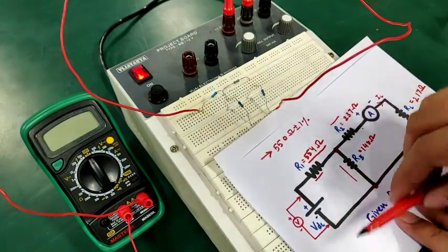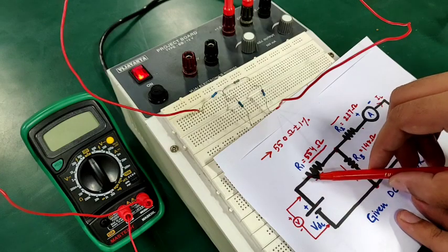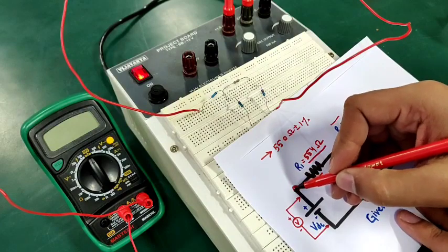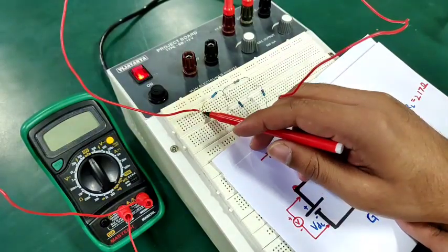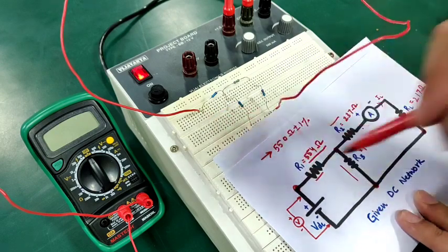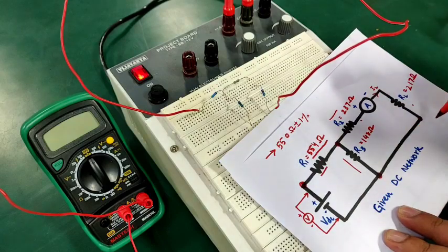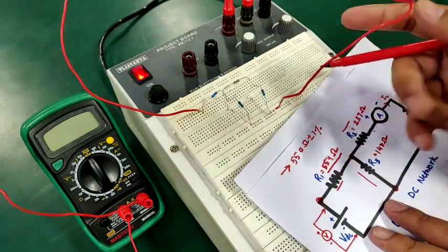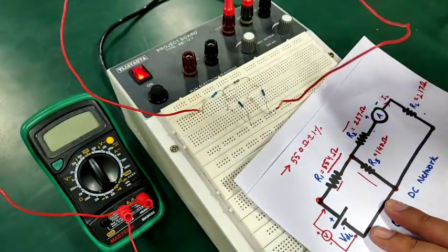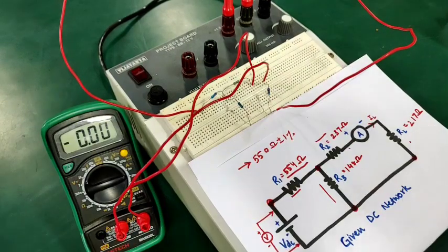Alright. Now coming on to the power supply, positive end of this power supply is going to where resistance R1 was initially connected. So resistance R1 was connected here. So let us check. Yes, my positive end of the supply is going to R1, and my negative supply is going to where R3 and RL were previously connected. So this is my negative end, and it is going to R3 and the junction of R3 and RL. So let us now move on to my step number 3.